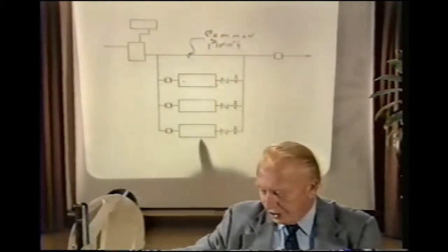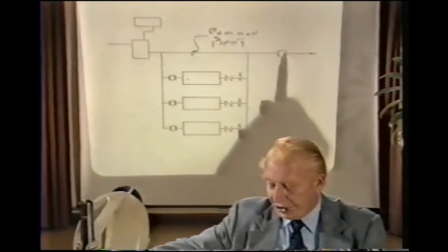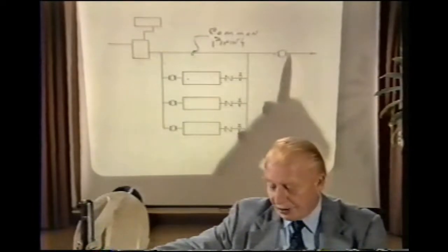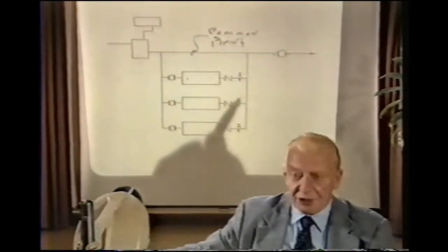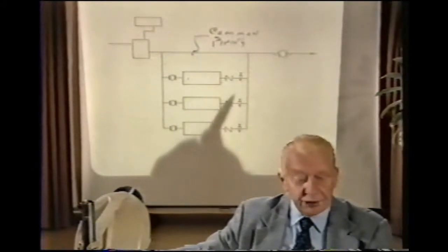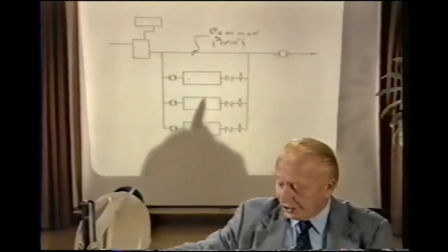This disassociates the pumping of the chiller loop from the pumping of the main distribution loop. And let's illustrate then how this would work on a system using variable volume flow rate.